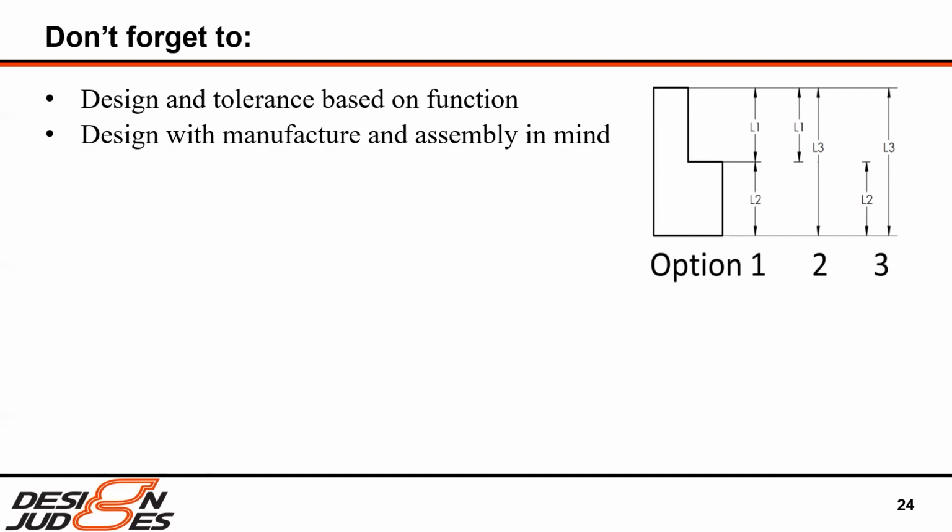So, the other thing is design with manufacturing and assembly in mind. You want to think about how you'll make each feature of your design while you're designing it, and that shouldn't be an afterthought. And you would think about how you'll put it together and take apart your design. And as most people listening to this probably know, vehicles often require a lot of disassembly and reassembly, and you'll really thank yourself later if you only need a small number of tools. And you can do this through standardizing your fasteners and having designs that are easy to service by providing access to the fasteners and having methods to remove components without having to remove 5 other components.